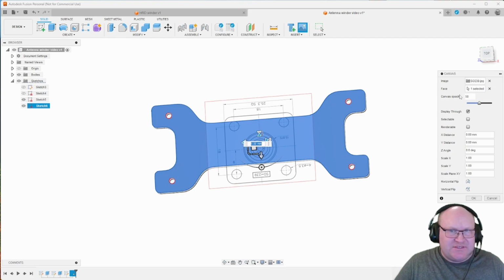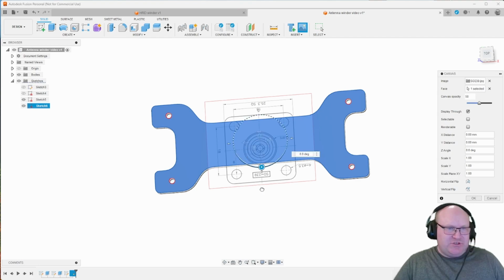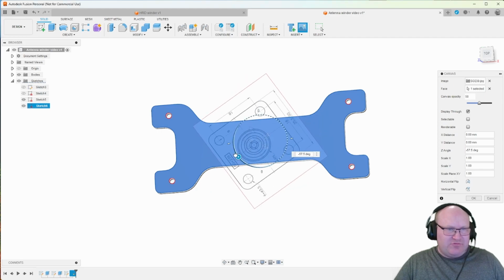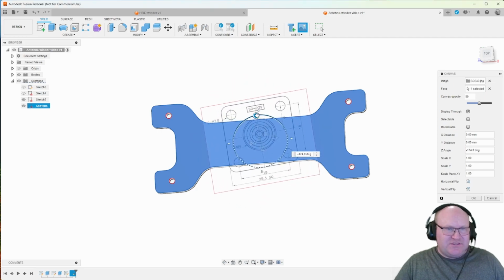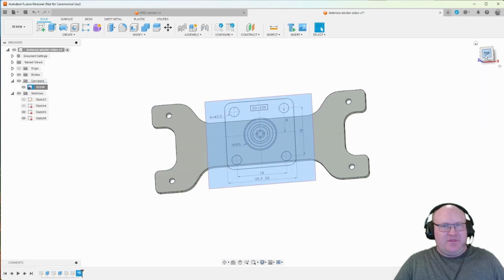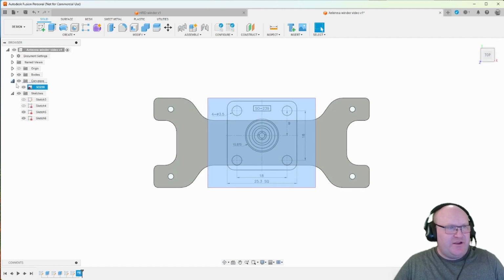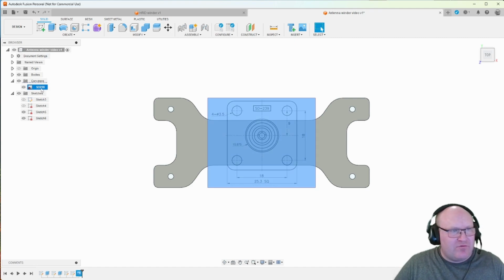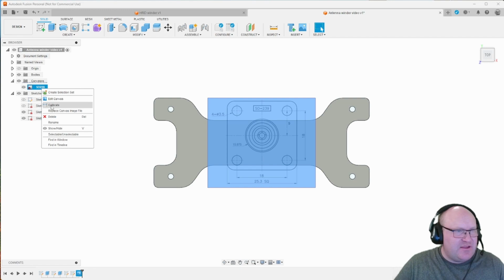Now, firstly, it's upside down. Just click this rotation tool here to rotate it the correct way. It will snap slightly to the points here, so just drag it carefully to -180 and it will snap there. Now that it's correctly placed, you can go over here and see you have a new folder called canvases. In here we have that file, SO239. Right click it and click calibrate.